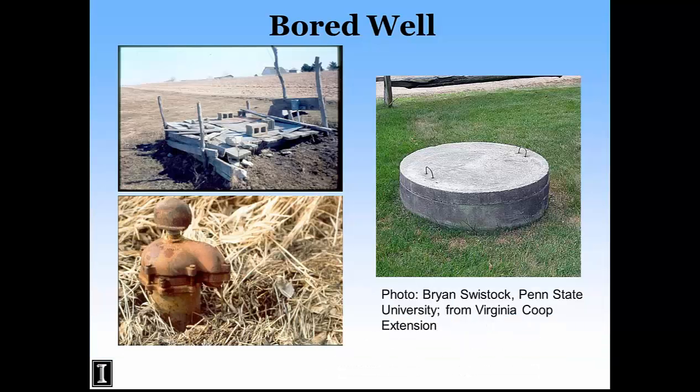So here's some examples. The one on the right is a bored well with a concrete lid. Again, in Illinois, you don't see any new wells like that because you have to have the 10 feet of material before you have the well. It looks more like the bottom picture on the left. And it's a regular wellhead that you'd find maybe even for a drilled well. And the first 10 feet is just a standpipe, basically, until you get to the bored well.